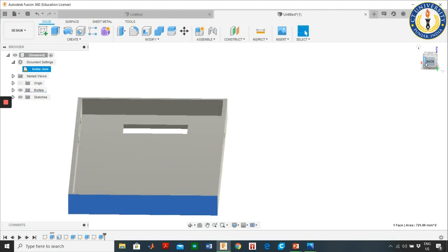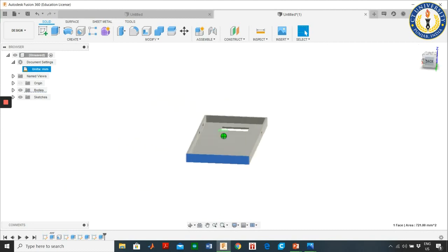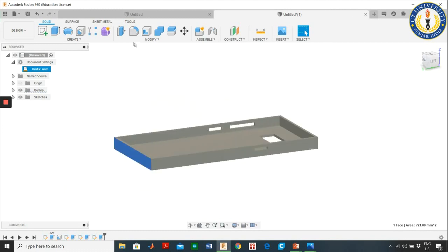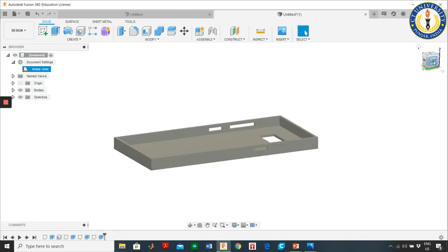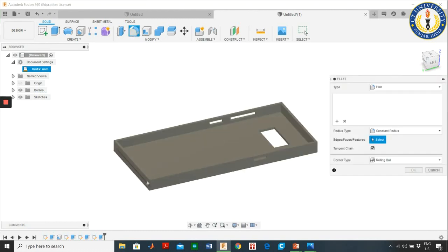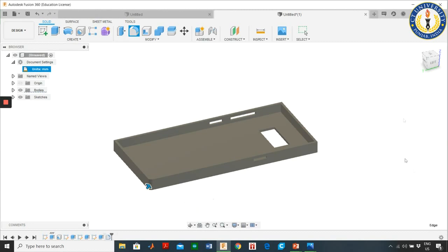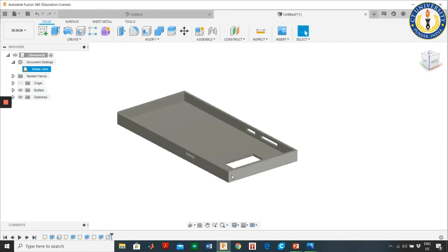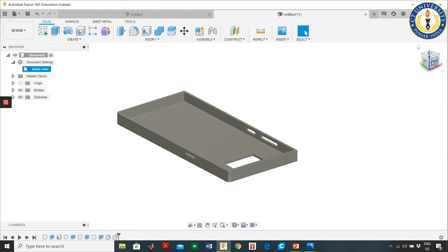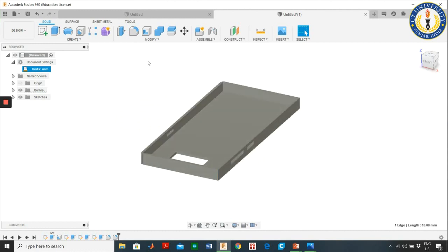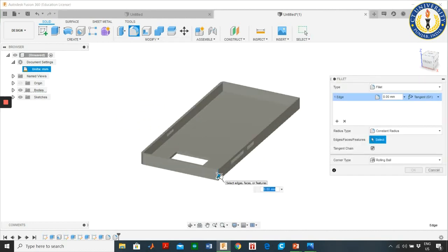Next, the feature is that it doesn't look nice because it looks more like a box. So there is a feature you can use, fillet. Select the edge and you can give, I will show you. Select the fillet feature and when you click here, you can see it's going like this. Just give 2 mm or 3 for all the 3 edges which are left. So select this fillet 3, again select this edge. There's a shortcut also, you can select F3.